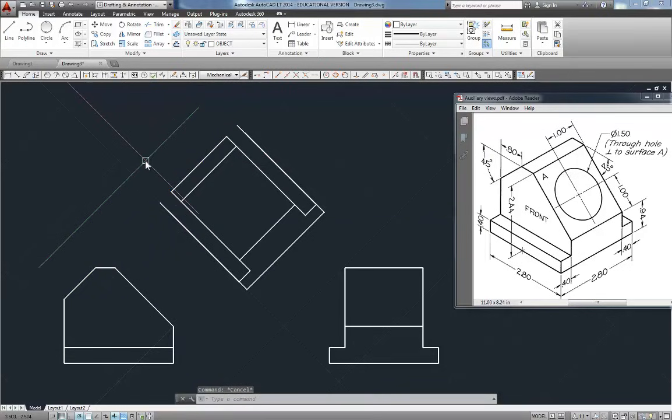So you really have to analyze when you work in auxiliary view. And if you look at a particular corner and look at where it is with relationship to my front view in this case, and then look over here, see how wide is that corner? How deep is it there? And that depth will be the same up here. Because it's really difficult to understand what's happening in these areas here, which right now are open-ended.